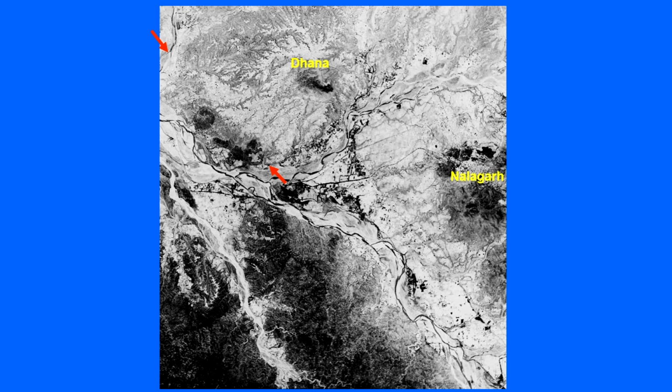What we inferred is that there is a sort of fault here, and this area has been warping, because in the folded terrains mostly what we see is that there is displacement taking place, and this can result in the formation of a domal structure or a folding here. Okay. I am putting this in section here. So, this is the top surface. This is exactly what we inferred. Okay. And there is another fault which goes here, which has given rise to a different pattern of channels here.